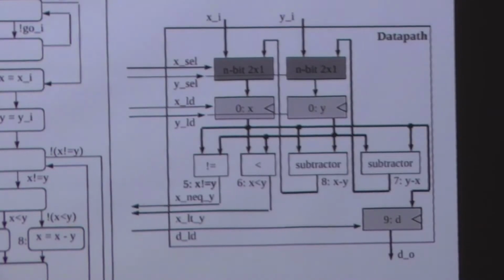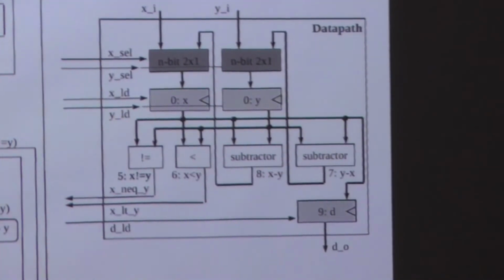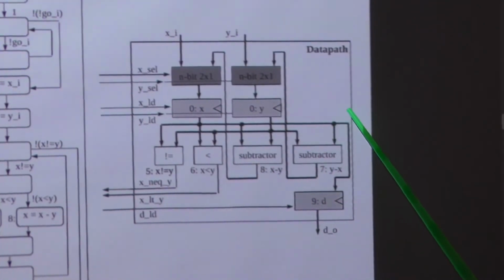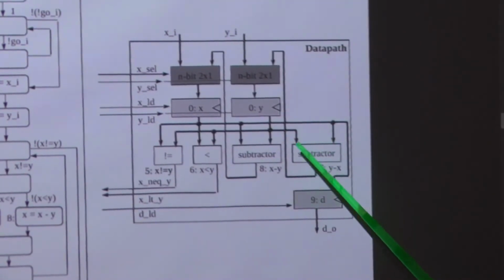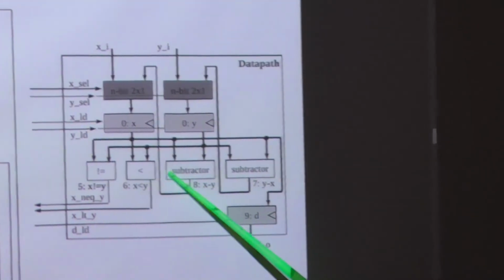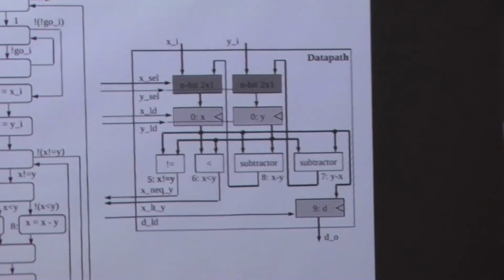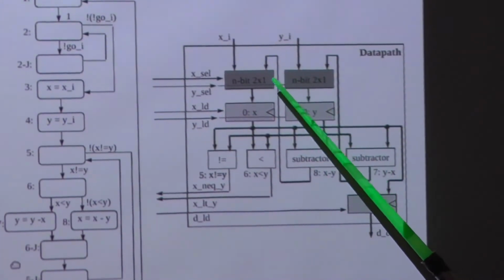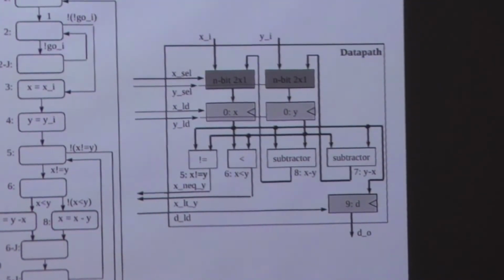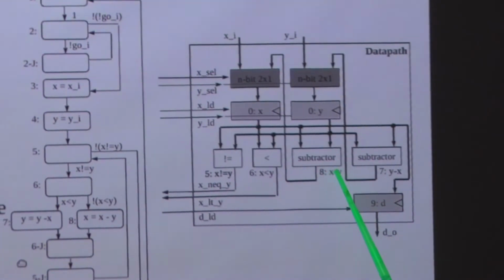But that doesn't necessarily have to be the case, right? That's been hardwired in, but if we were to throw a few extra multiplexers in there, multiplexers are not overly complicated components, at least not compared to subtractors, we could easily design the circuit such that this input was either x or y based on a selection, and it would feed into one of these two registers based on selection as well. I believe when you go from 1 to 2, that's called a demultiplexer or something like that, an inverse multiplexer. But anyway, that's our starting point, right?